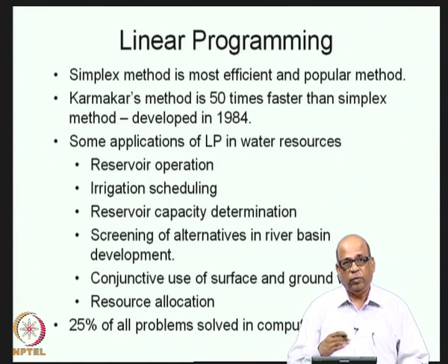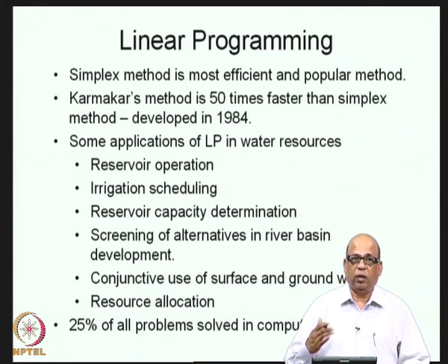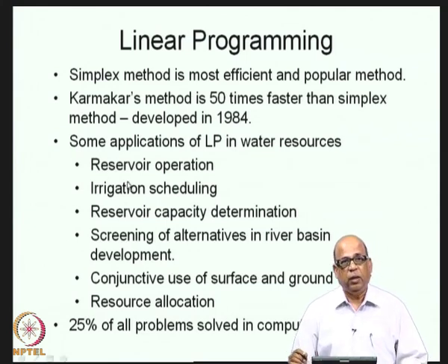So, you have sequential optimizations, monthly decisions to be taken over 12 months of a year, and therefore, you may have associated with each set of constraints, 12 constraints, and like this you may have several constraints corresponding to mass balance, corresponding to the constraints due to the physical features of the system and so on and so forth. So, you will have a large number of constraints associated with even a single reservoir operation problem. So, the size of the problem will be quite large.